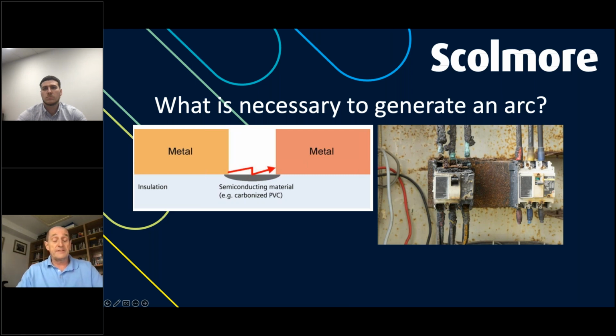That's absolutely the case. Although it is interesting, we have come across instances, haven't we, Jake, where somebody's plugged something in and it actually has taken out the AFDD, and of course we have no control within the fixed installation over what somebody plugs in. So there's an element there that AFDDs are clearly working, they're doing their job, but when you then come to the consequences of arcing, they can be ferocious.